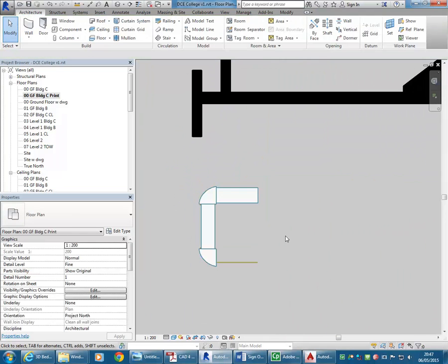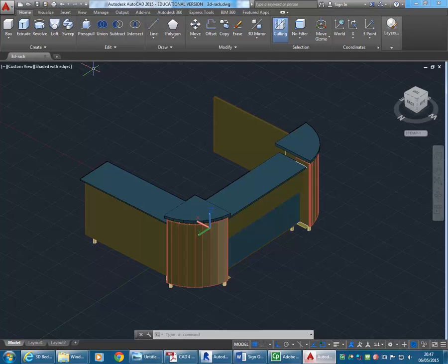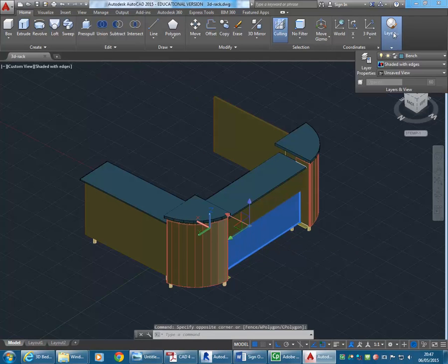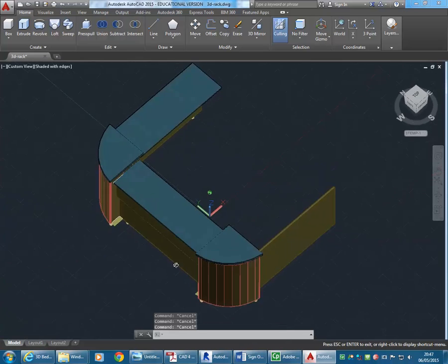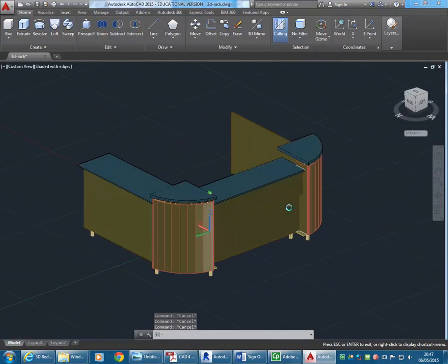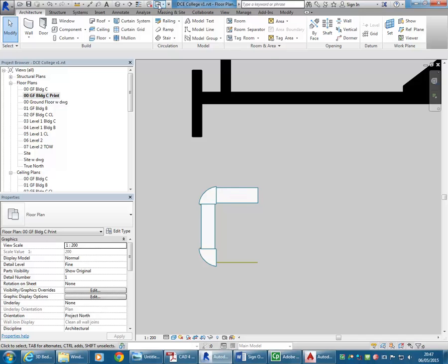And then if I do want to fix up that surface there, it's because I didn't put it onto the right layer, so I'll fix that now, and I think the rest is actually okay. Save the file, back to Revit, switch to the family.